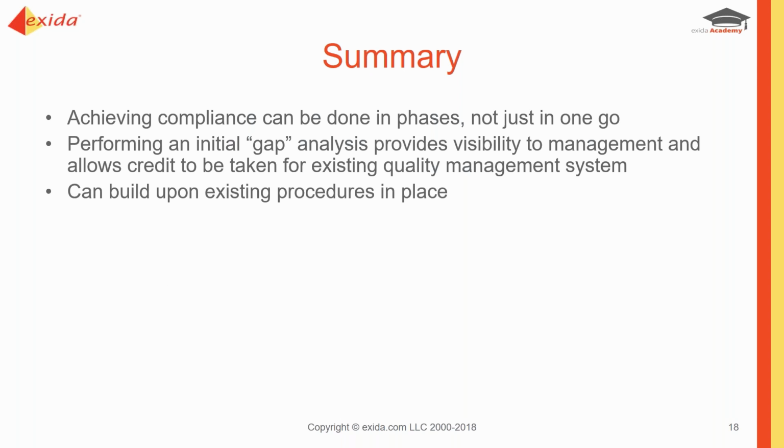Those existing procedures will not be wasted. We would leverage what we currently have. That's the primary benefit of doing this gap, is to look at what do we currently have in place, what can we utilize, and refer to those. So for example, if we have a lot of the procedures already existing, but we actually don't have a functional safety management plan per se, we can create a document that refers to the existing procedures.